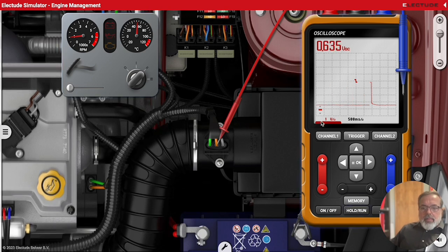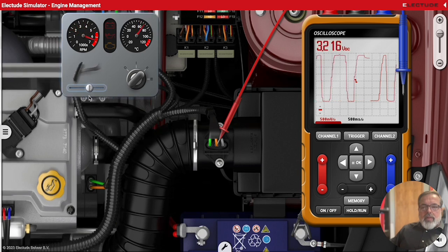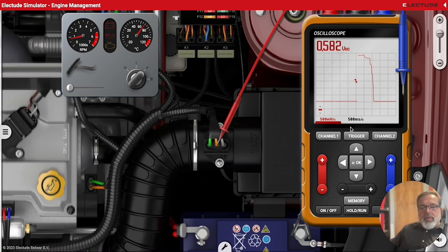If we were to make that a little bit bigger, we could probably change that to a half a volt per division, so we'll zoom in here a bit on that. Even better yet, get a little bit more definition there. I'll add 500 millivolts per division.